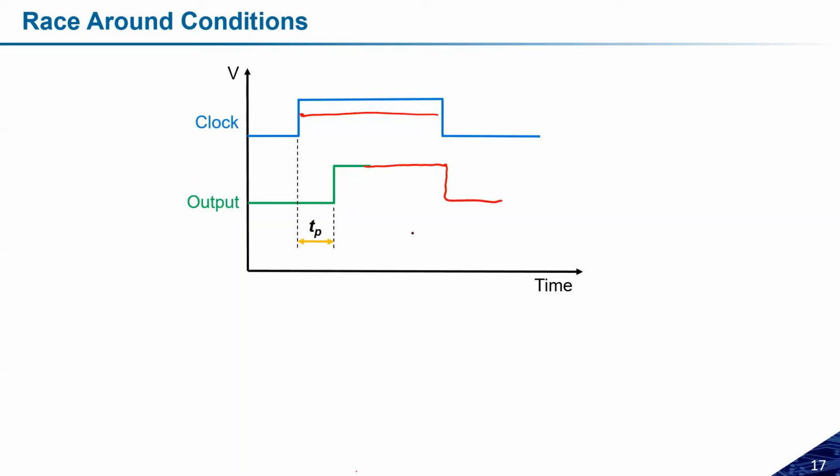This is the ideal requirement, but in practice it is not possible if the clock pulse width is very high. The output can toggle from 0 to 1 to 0 again, even while the clock pulse is activated and not changing, at the same state. So the output could go 0 to 1, it can toggle, and again it can toggle, and this is what we can call the propagation delay of that flip-flop.